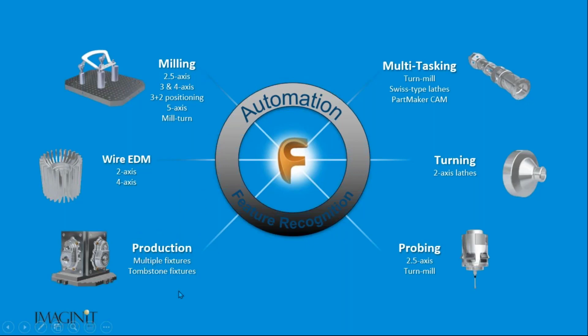For production, it also has the ability to create what's called tombstone fixtures if you're doing any kind of high volume machining while trying to maintain precision. Once you get done with programming a part, you have the ability to reopen that part in multiple fixtures and a tombstone fixture file, if you're doing a lot of horizontal tombstone machining. It also has wire EDM capabilities for 2-axis and 4-axis.